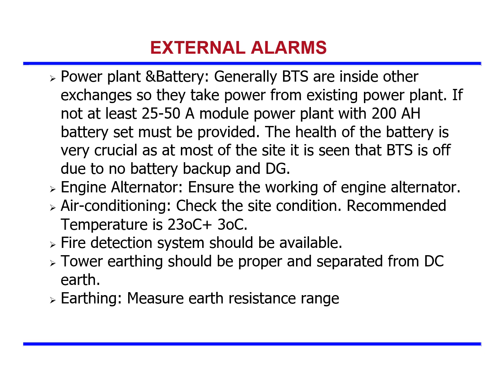First, external alarms. Power plant and battery. Generally, BTS are inside other exchanges, so they take power from the existing power plant. If not, at least a 25 to 50 ampere module power plant with a 200 Ah battery set must be provided. The health of the battery is very crucial, as at most sites it is seen that the BTS is off due to no battery backup and DG. Engine alternator working should be ensured.